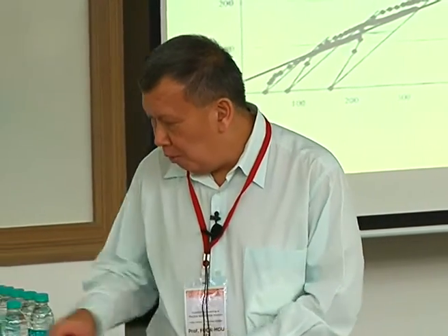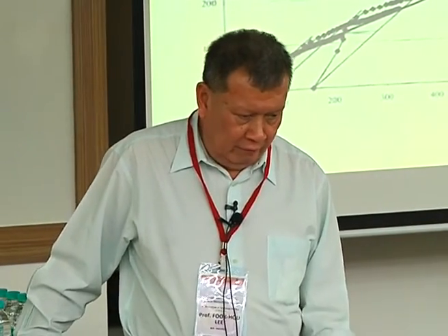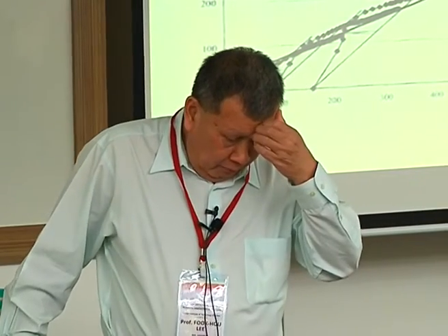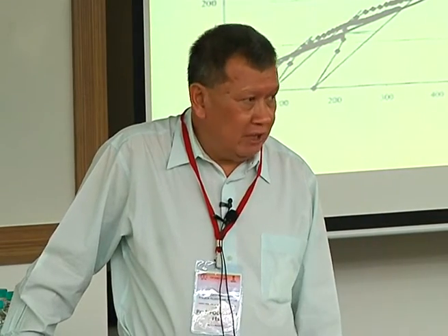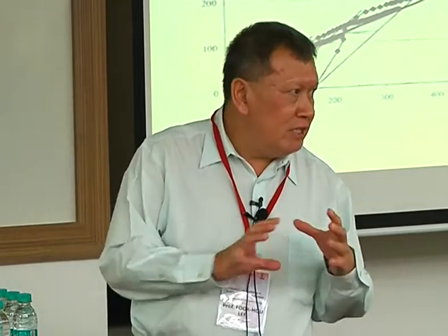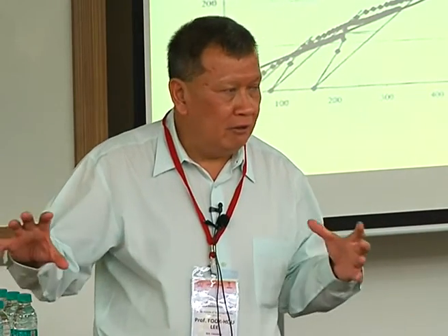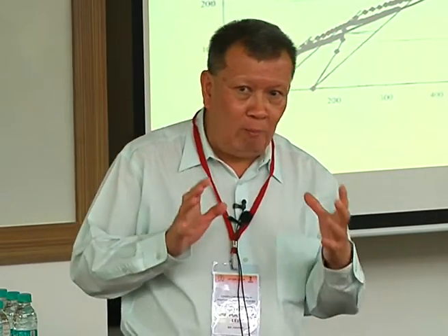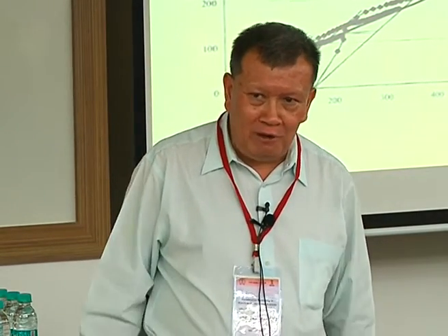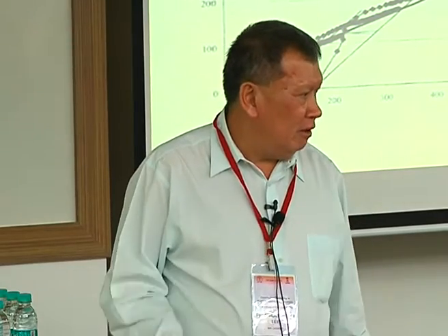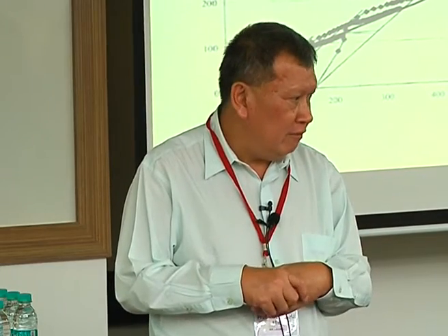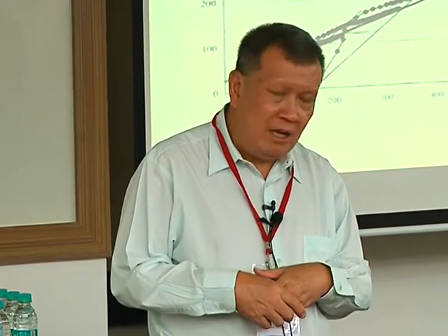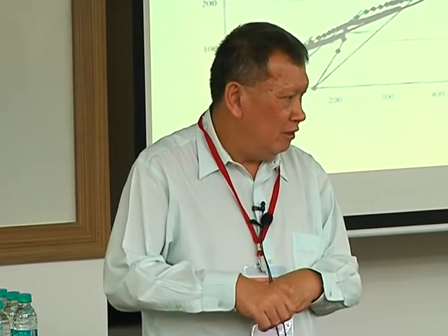The only thing is that in Singapore, we are somewhat more fortunate, because when they built the MRT, they actually did very detailed studies of all the major soil formations. And there are a few reports that came out, the likes of which I've never seen elsewhere in the world. It's a huge collection of things telling you even the Skempton pore pressure parameter, how it actually varies from what range to what range. And this to me is incredible data collection. This is very good. And that was back in 1985. But of course, you ask me how many people use that, I'll say probably very few ever used it.